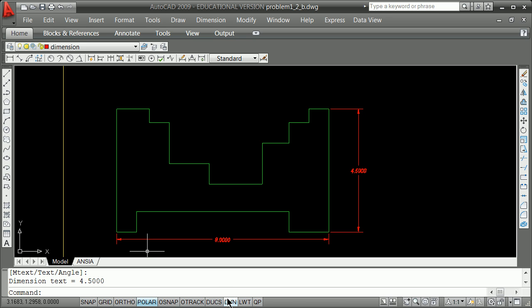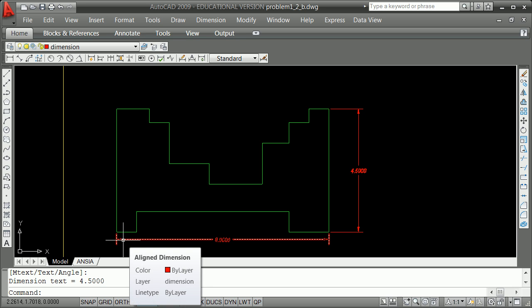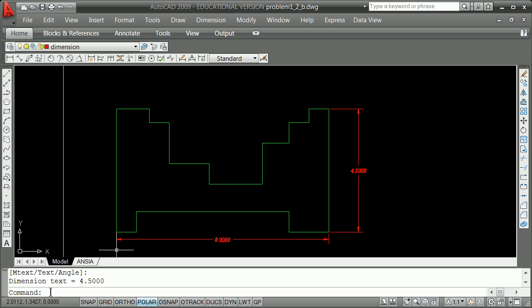I will try the dynamic, but remember that we also could have done this. We could have just typed in more or less line from a certain point and then at distance less than symbol and then a direction, and our directions would have been 0, in this case 90, 0, 270, 0, 90, 180, 270, 180, 270, 180, 270, 180, and let's look if that worked. When I list it,